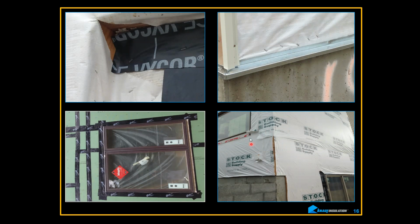Nice little gap here, nice little gap here. This should have been folded over and the tape on top of it so that things are shingled. If water gets behind the tape, it fails, it flows back, shingled all the way down. So this is the one I like the most. I see this quite often. This is what I call tucking your raincoat into your pants.